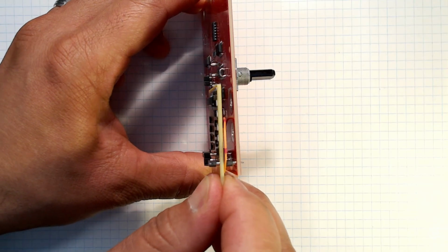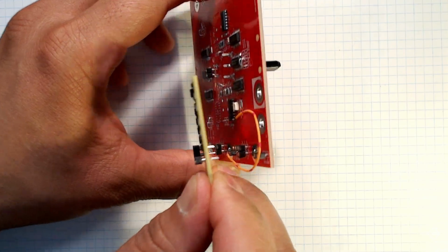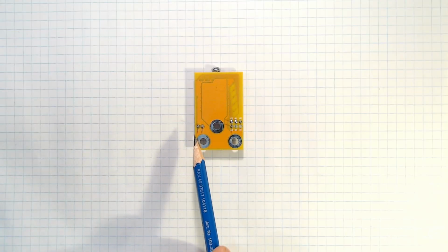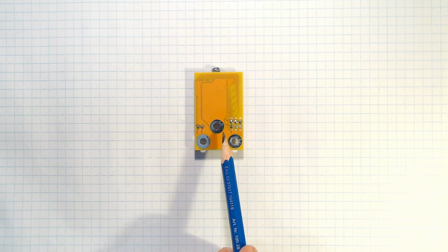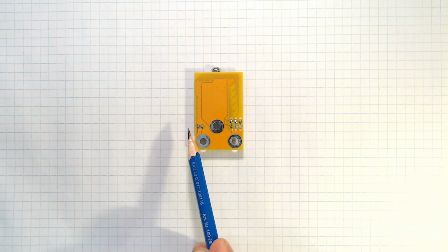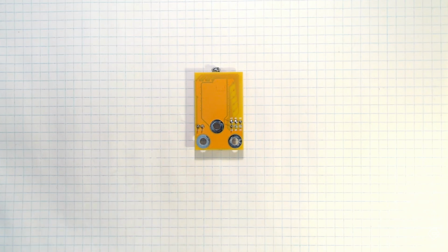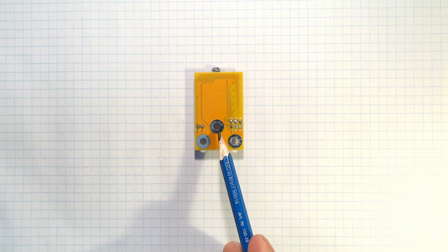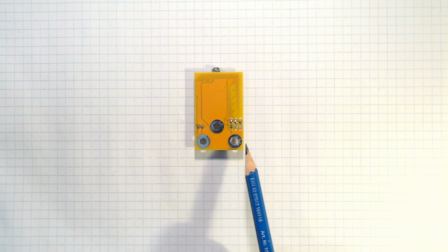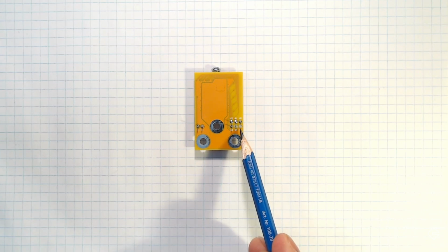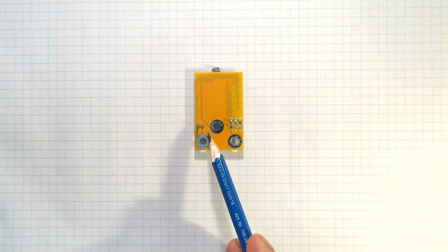We're going to leverage the polygon command once again to create this portion of the part. If we separate the boards, we can get a better view as to what this part is going to look like. The polygon on this side of the driver board is going to go around this terminal, around that terminal, then back up and around the thermal conduit, and then back down again. We're going to need to know the vector that locates the thermal terminal. We're also going to need to know the radius of that terminal, along with the radius of these terminals, and the thickness of the material behind the terminals.